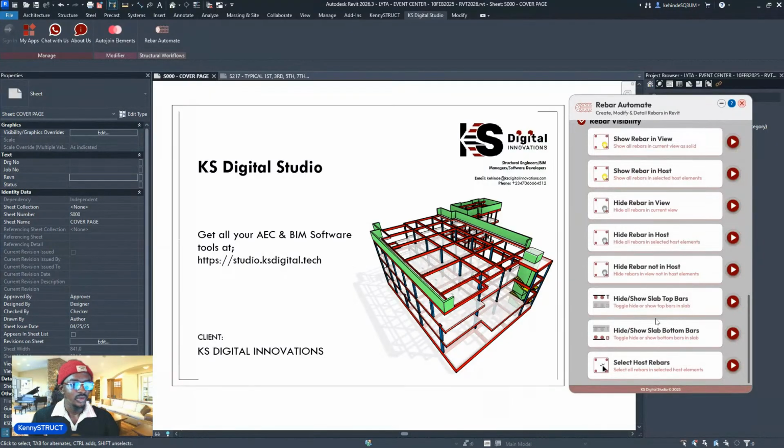So you also have this hide and show top bars for your slab. It's very important. Most engineers like to present their drawings with the bottom bars alone and the top bars alone, just for clarity's sake on construction sites. This can help you to do that easily. You can hide your top bars or hide your bottom bars, or show your top bars, show your bottom bars. They work as a toggle. Once you click on it, it hides or it shows it basically.